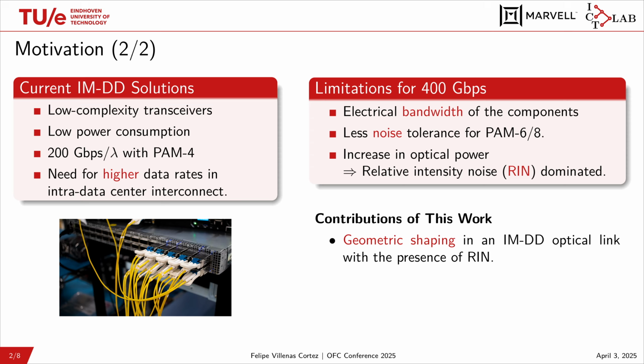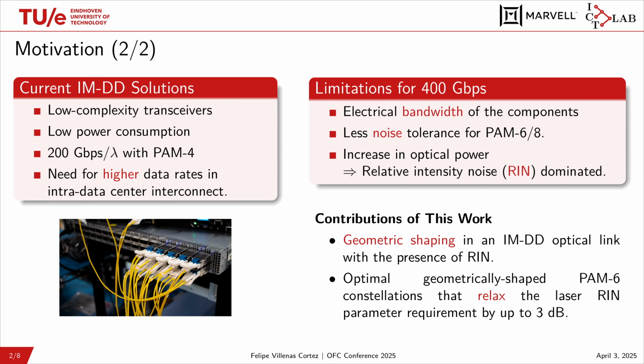So the contribution of this work is that we employ geometric shaping in an IMDD optical link subject to the presence of RIN. And we propose an optimal geometrically shaped PAM6 constellation that allows us to relax the laser RIN parameter design by up to 3 dB.